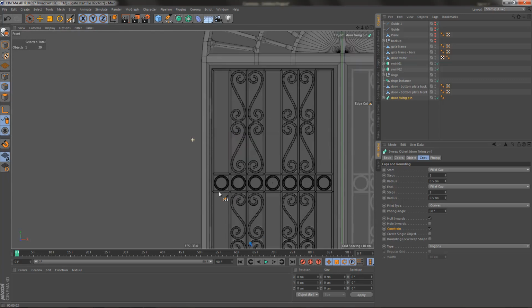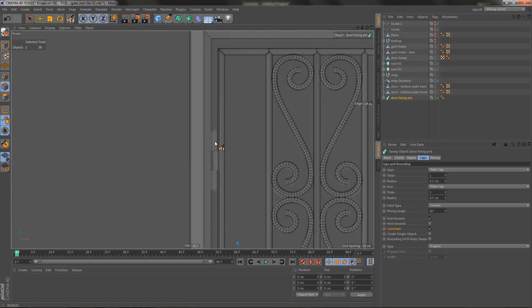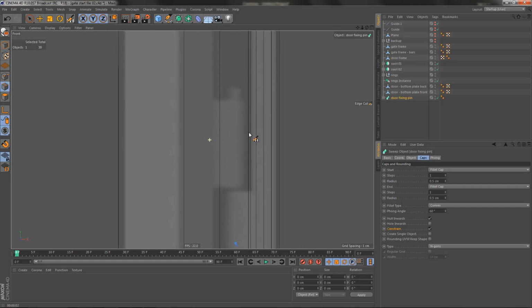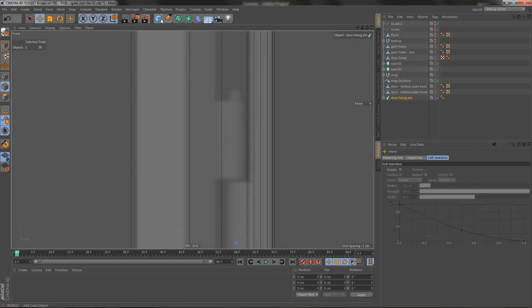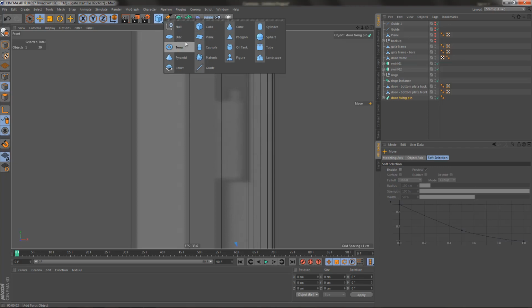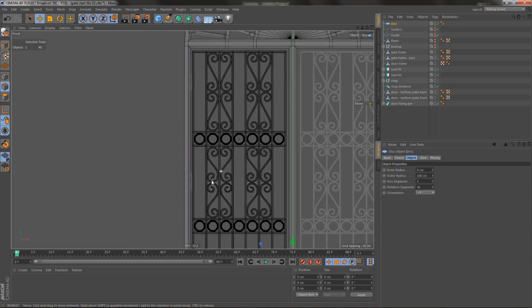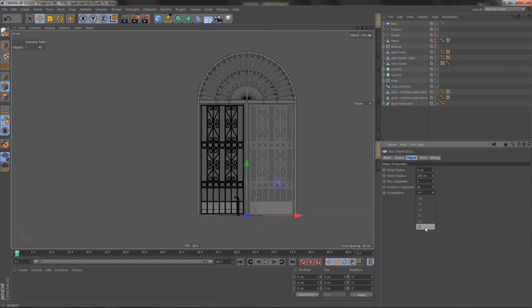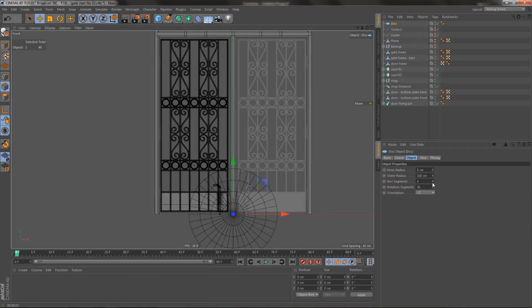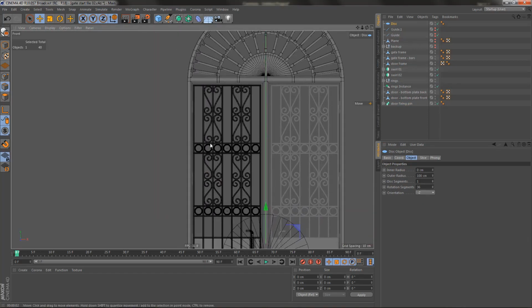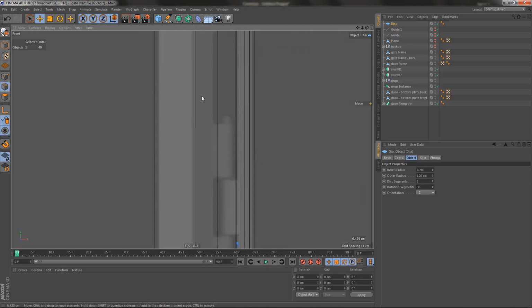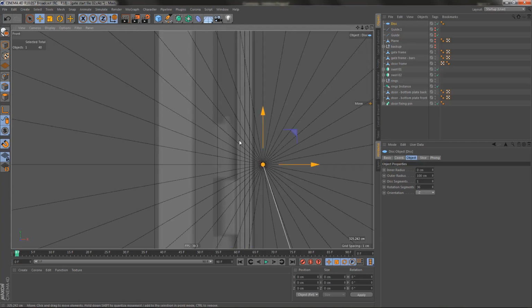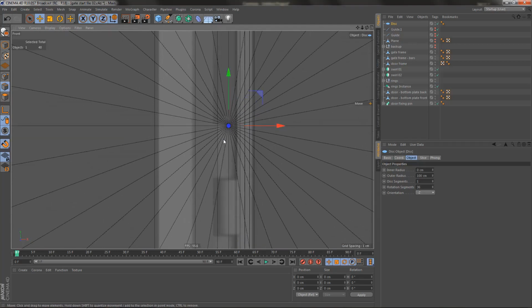What we still need is the hinges over here on the left. And these are basically square or rectangular with 1 round end. So I think what I'll do here is I'll start with a disc, put it to -Z for now, get rid of the segments, and I'm going to move it up to, let's just switch on snapping, and I'll move it to here.